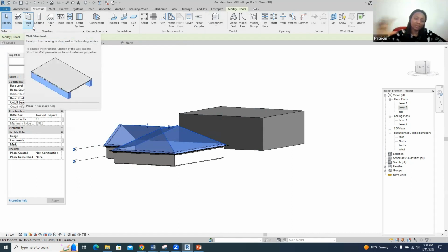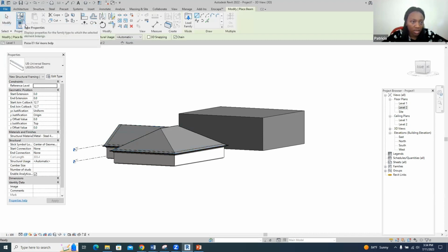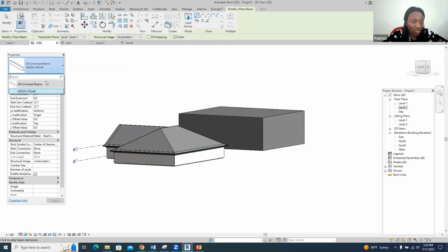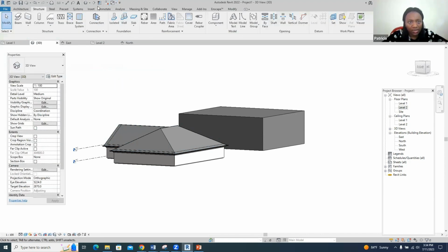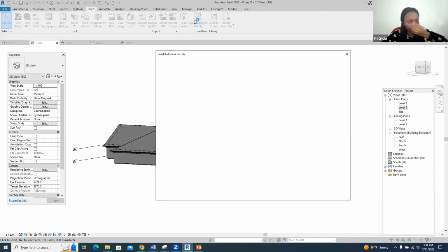You have to make a set plane. So I'll work on that. Like the next time we meet, I'll make notes on it to show you how the steps are. But it's inside the structure, and then we'll get the beams, and then we have to bring in. So over here, your default Revit is steel members. So you have to go to insert, and then load the family. For the recent versions, we load the family of members.